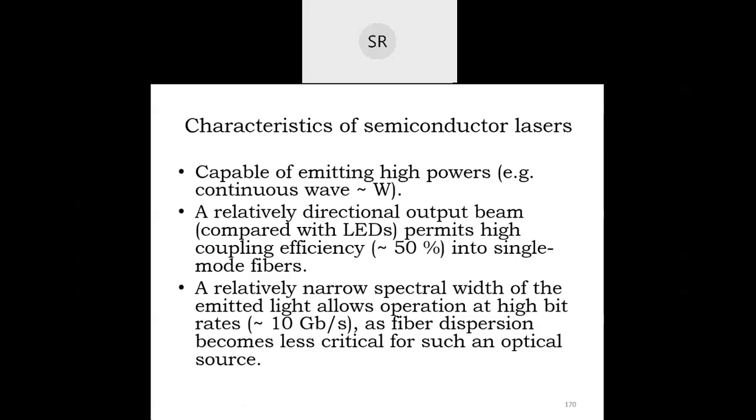Generally, in optical fiber, lasers or LEDs can be used with single mode or multi mode fiber. Similarly, lasers can be used with a fiber as a transmission line, and we generally prefer single mode fiber so that we get a high power output. All these devices have a narrow spectral width. The laser beam is narrow, but the emission pattern of an LED is different.